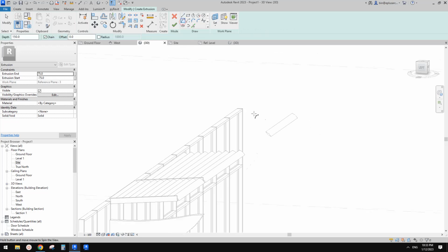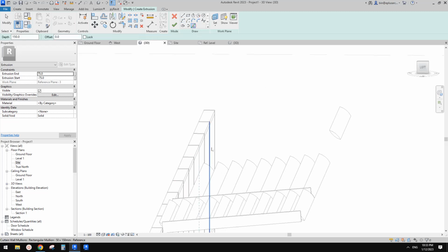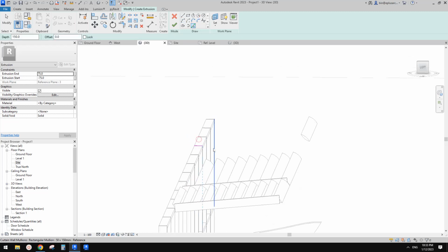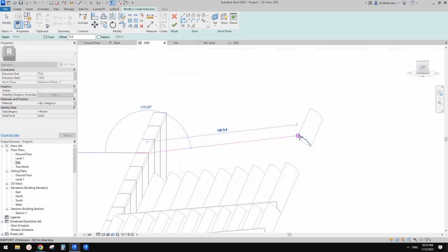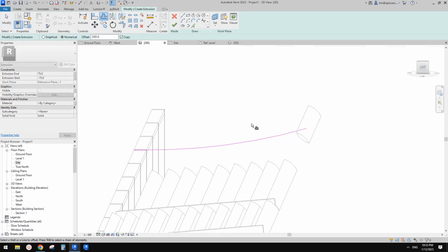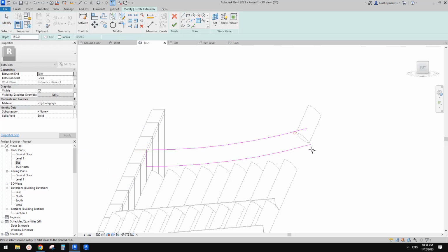This time I'm going to draw an arc. Maybe I'll just pick a line. So now I pick this line, so I know where this one starts, and then use a start and radius arc. So I'm going to maybe roughly here. Okay, so maybe this is a radius, and then I'll just offset. That's it. So now I just close this, delete this, and fillet arc this.